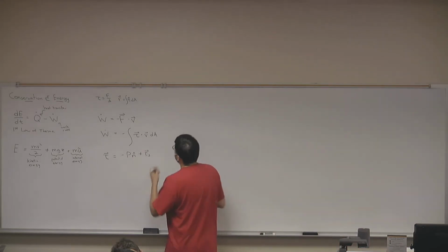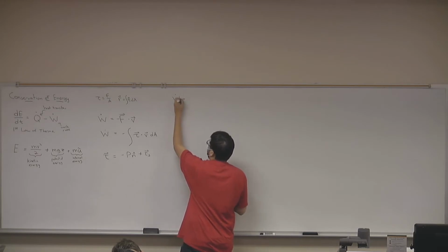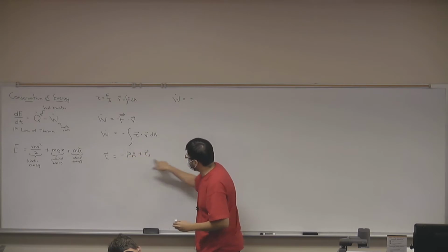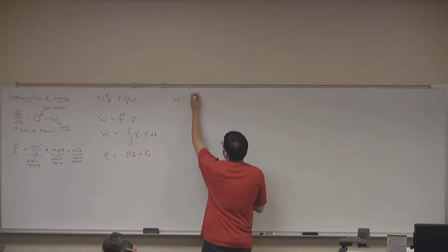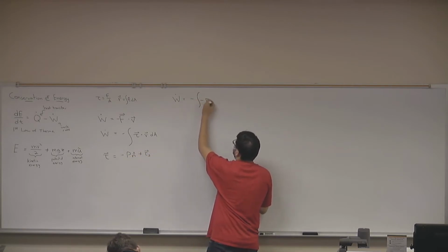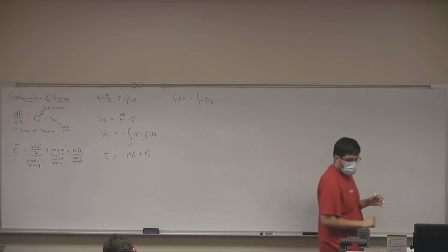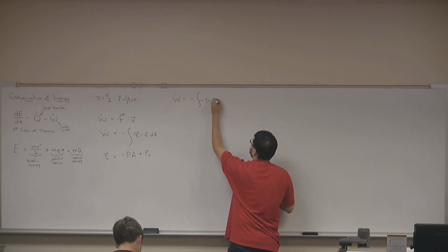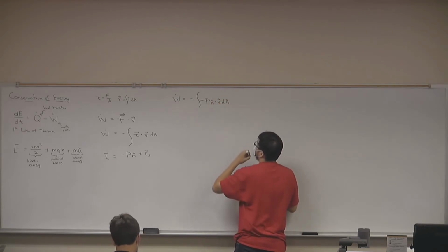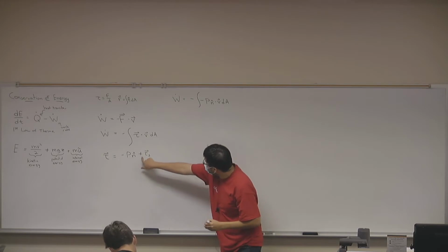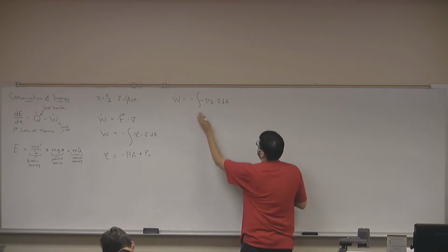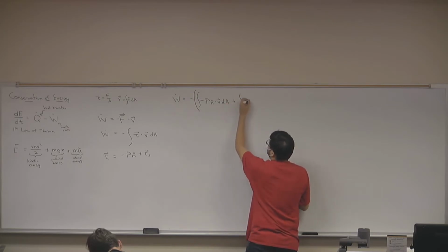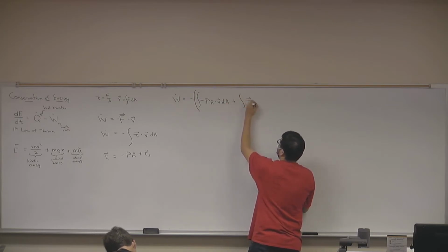By looking at these equations, my work rate can actually be negative, and I'm just going to divide my stress term into these two components. I have negative the integral of my pressure, that is my normal stress, dot V dA. And then I have plus, but we have a negative sign, so plus the integral of my shear stress.